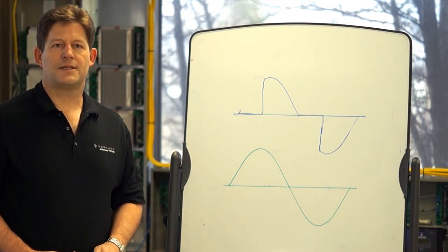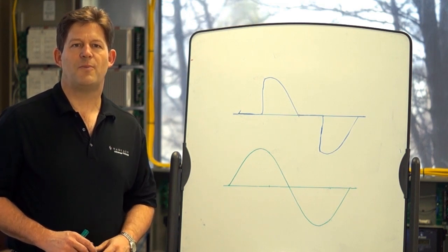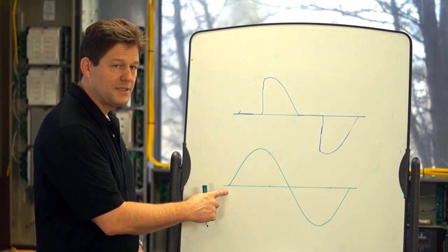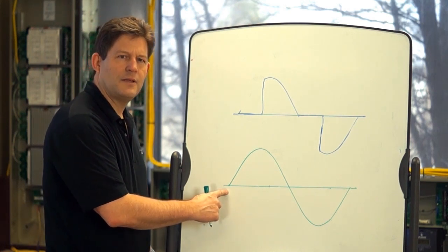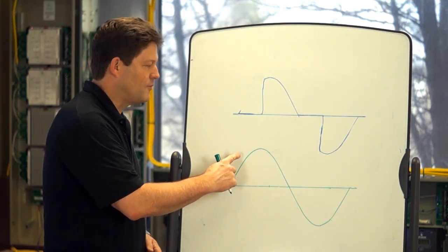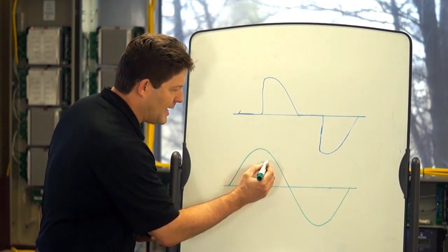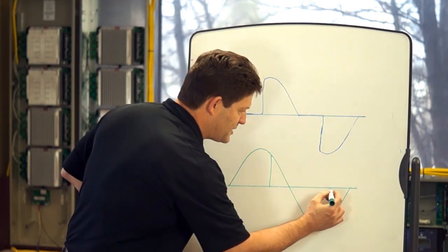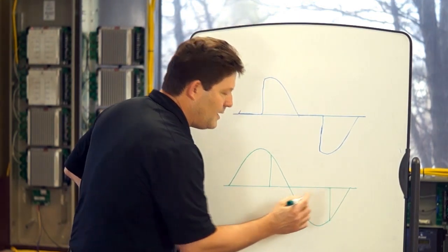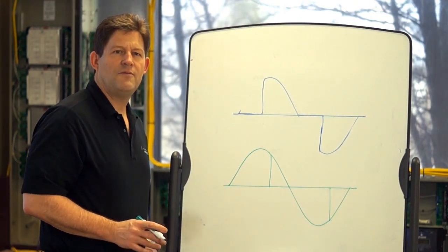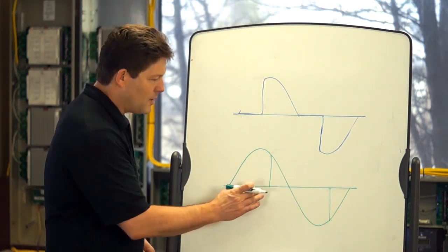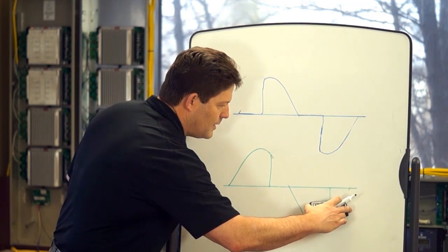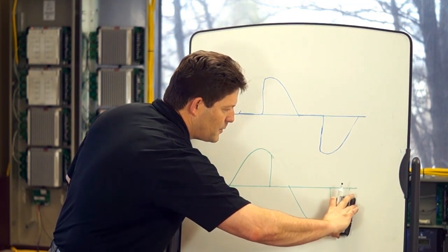The solution to dimming electronic transformers is to swap the sequence of power delivery to the lighting load each half cycle. Instead of opening the switch at the beginning of the cycle, the switch is closed, and at that point the power is delivered for a time. Then after a predetermined delay, the voltage is turned off and power is no longer delivered for the remainder of the half cycle. In this way, no sudden voltage rises occur, so it works with the electronic transformer. This then is the waveform from an electronic transformer compatible dimmer.